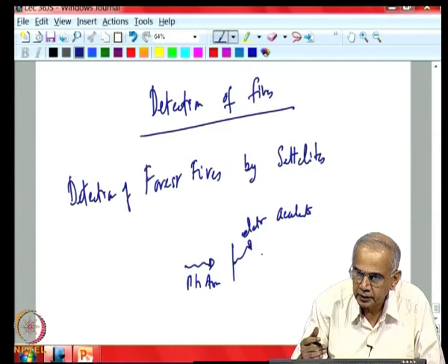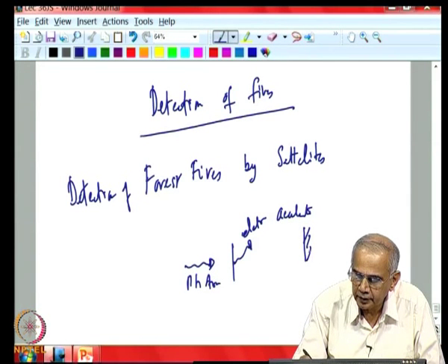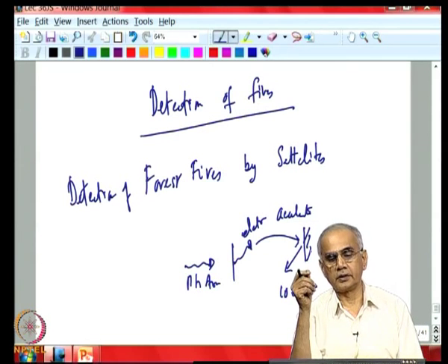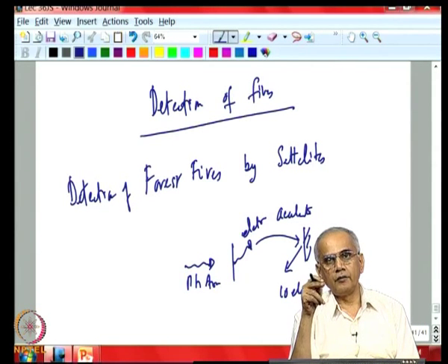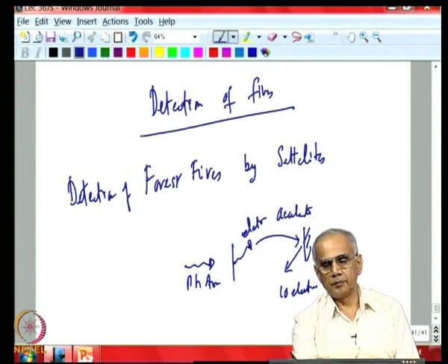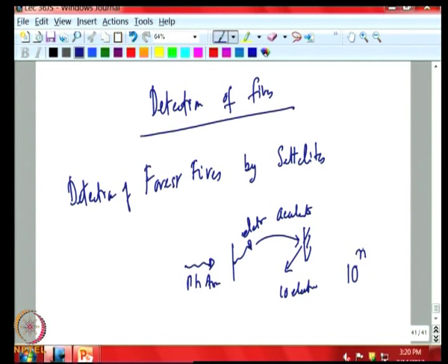So, that is high energy, then it hits another detector, and for each electron that comes out here, 10 more electrons are released from another detector, and you can multiply this many times. So, if each time the number of electrons increases 10 times and you do this 10 times, you get 10 to the power of 10 amplification.